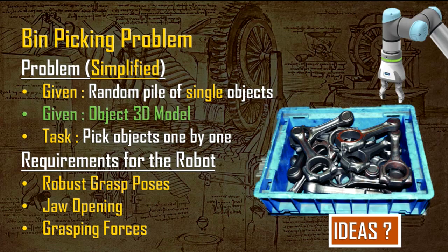It is possible without 3D knowledge as well, using image stitching methods and PnP algorithms, as you said. But with 3D depth, we not only assess the depth of the object in the bin, but can also identify the orientation and position, as well as how it is oriented in the 3D world.